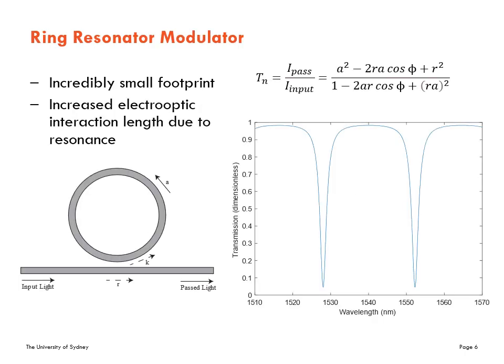Ring resonators are waveguides which loop back on themselves, forming a ring which exhibits resonance for input light for which the ring's optical path length is an integer multiple of the wavelength. Ring resonators allow exceptional wavelength selectivity with small footprints. Light is coupled into the ring evanescently from a nearby waveguide, and light of resonant wavelengths is coupled almost entirely out of the waveguide and dissipated in the ring.